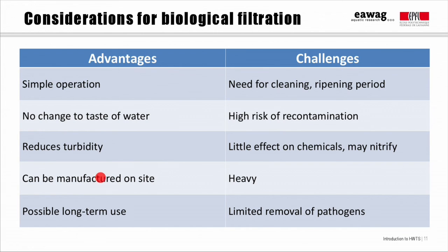Biosand filters can be manufactured on site, the concrete models at least, but those concrete models are very heavy, more than 150 kilograms when they're full. So once they're put in place, it's very difficult to move them around. It's also difficult to transport them to the household level if they're collected at a central location. There is evidence that the filters are used for years consistently, but the same studies have shown that the effectiveness in removing pathogens is rather limited.